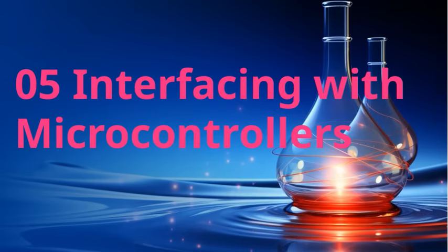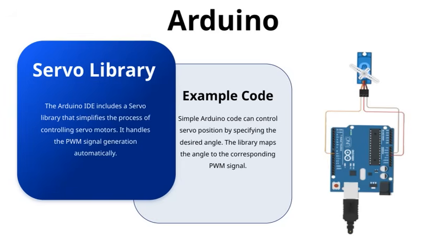other devices. Now, on this slide, we're looking at the Servo library that comes with the Arduino IDE. This library is a real game changer because it makes controlling servo motors much simpler. Instead of manually generating PWM signals, which can be a bit tricky, the library handles all of that behind the scenes for us. It automatically manages the PWM signal generation, so we can focus on what we want the servo to do rather than how to generate the signals.